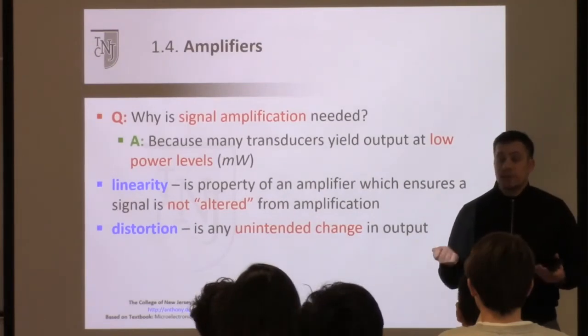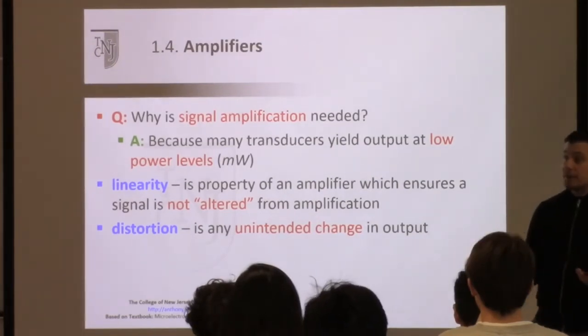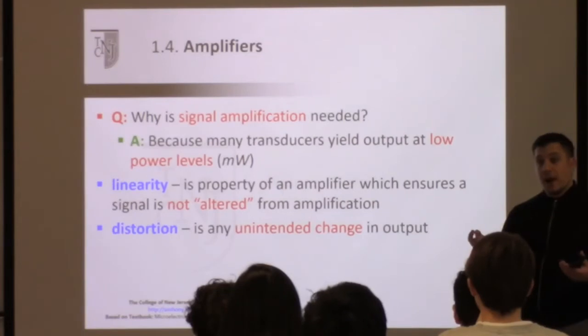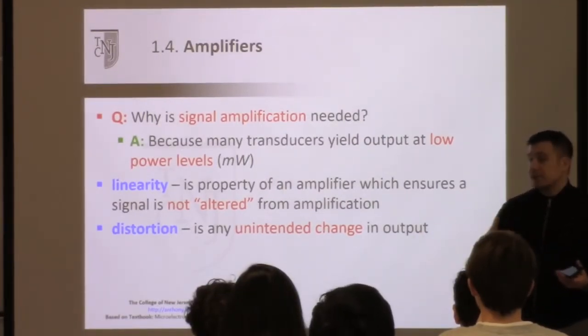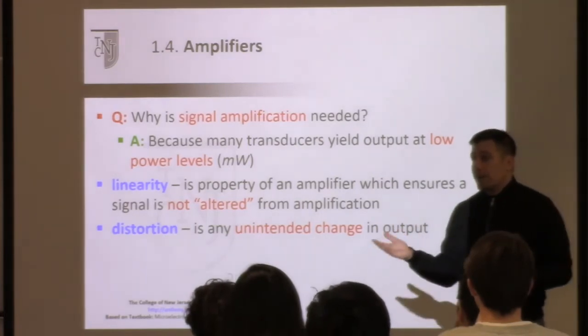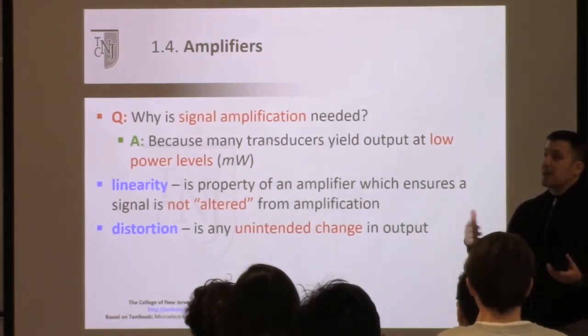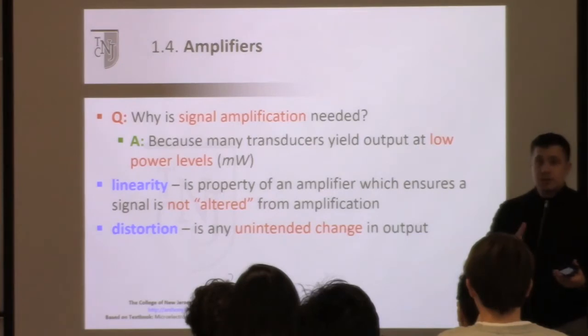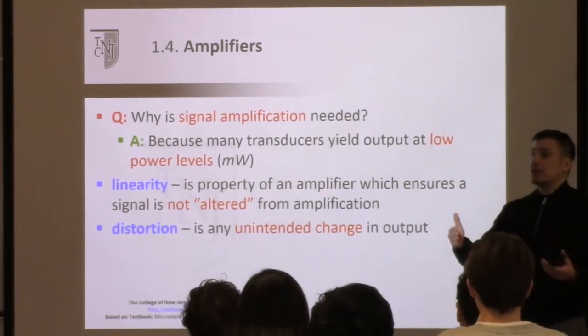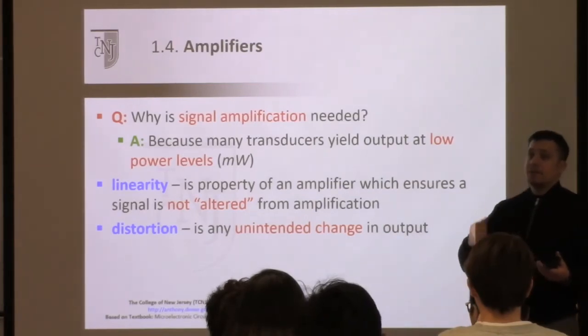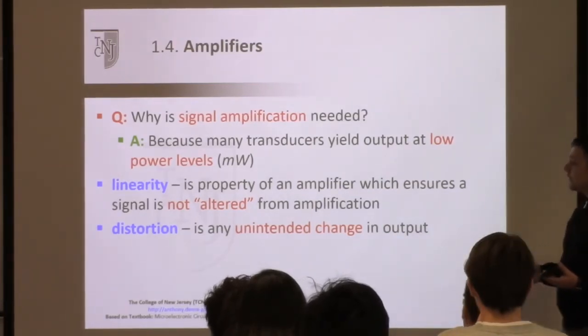Let's say you're trying to record with that microphone something that's very soft. Then you may need a voltage amplifier in order to make the amplitude of the signal bigger. So there are amplifiers that can do both. They both fall within the same range, but they have slightly different purposes. There's voltage amplification to increase resolution. There's power amplification to increase strength or intensity.